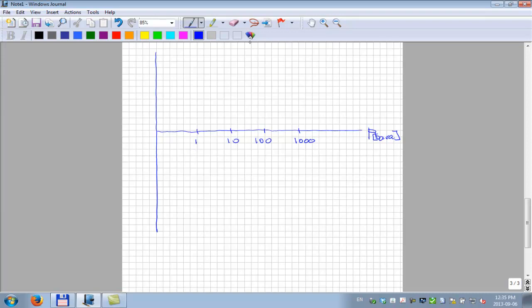And PSI, this would be, I'll just make it in gray, 15 PSI, 150 PSI, 1,500 PSI, and 15,000 PSI. This covers pretty much the range of two-phase conditions in petroleum systems. And that's obviously a log scale, as I've drawn it, and we're going to have K values also plotted on a log scale: 0.1, 0.01, 0.001, and 0.0001.